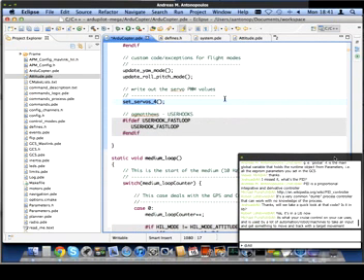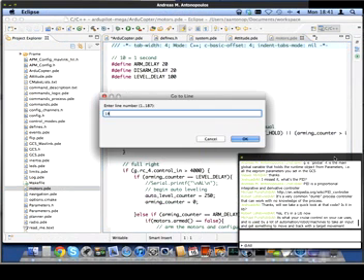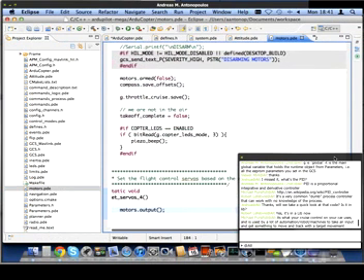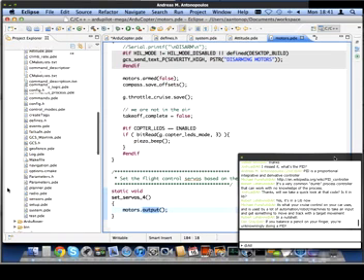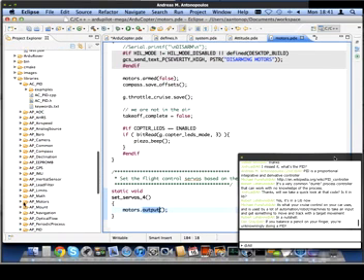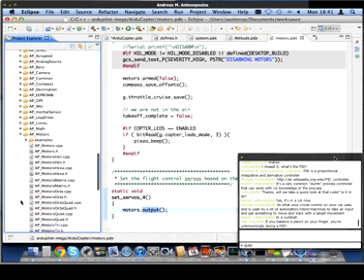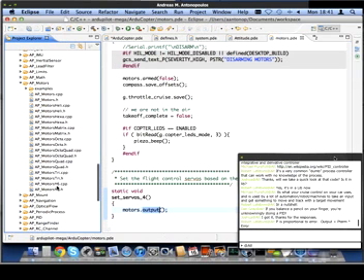You'll find actually that back at around line 1080, we call the set servos 4 line. So that is where we make use of the outputs from those PID functions and send it to the motors. So we should go to the motors.pde at about line 184. There it is there, you see. So set servos 4 is a very small function, and it just calls the motors.output.